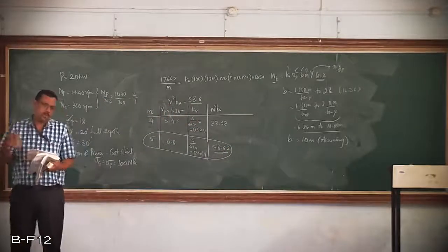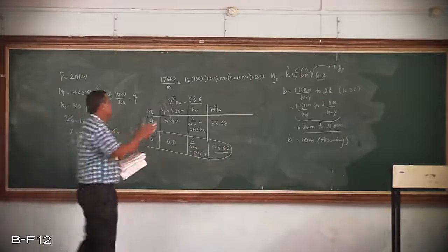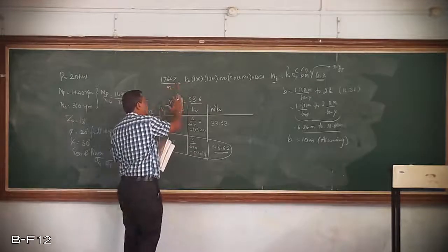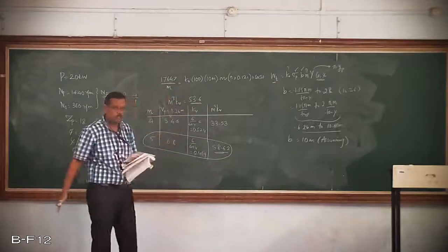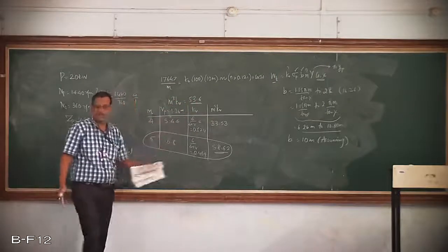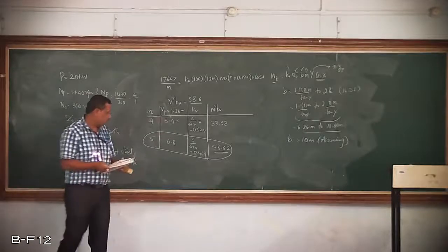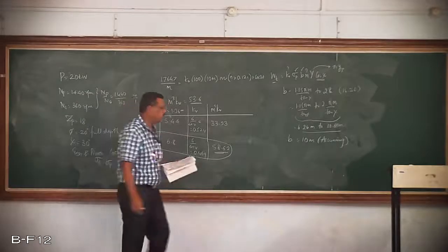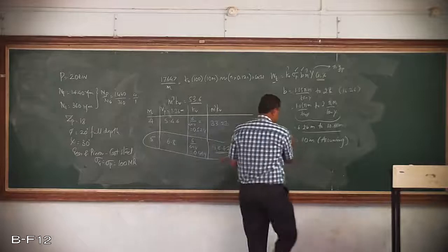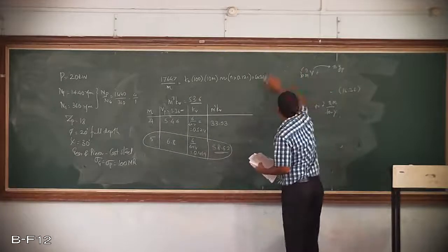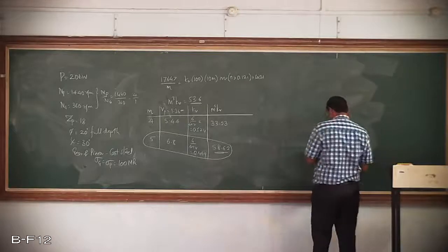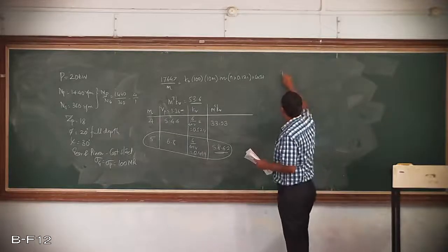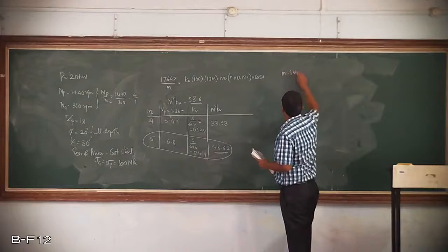However, you are free to assume the value of kV, substitute it, get m cube, then resubstitute and check for the strength. Using either method, you can do it. So once we know the module is 5, it is satisfying our equation. Now based on that, let us specify the dimensions of the gear. Therefore, the module we get is 5 millimeters.